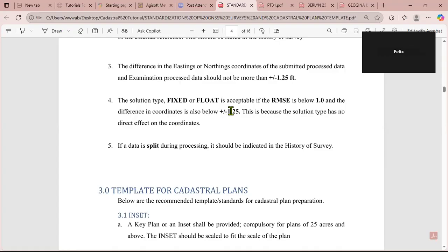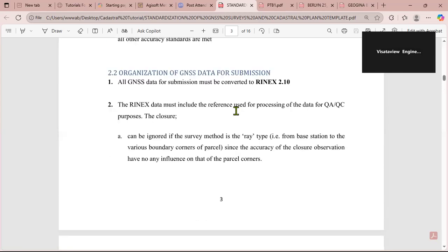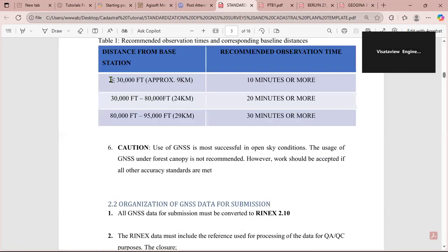If I understand myself, the emphasis is not on the distance from the site, but rather on setting up a TBM that you can base on to work, please. So they are saying that if you go beyond the distance they have given, this is the maximum distance you must go. If you go beyond this maximum distance, then you must set a TBM.